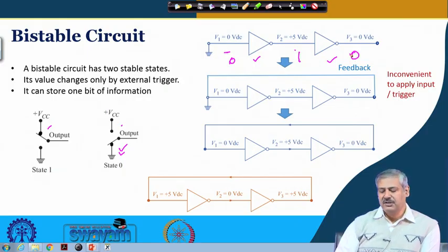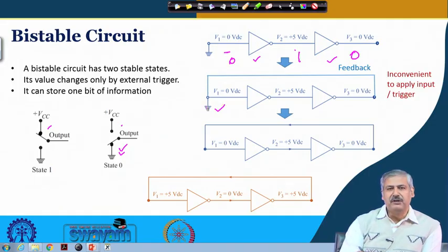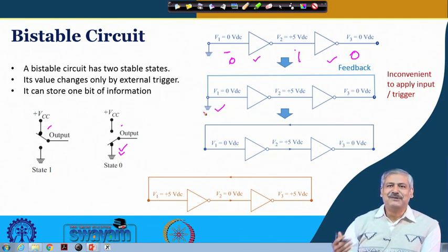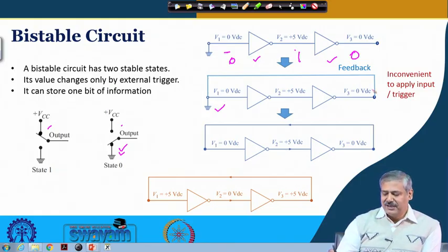Okay, this is understood. Now, while this ground is there, you connect a feedback. So, this feedback is key. This feedback is very important in developing the basic cell and the sequential logic circuit, right. In the combinatorial circuit, we didn't include feedback. So, the feedback comes in the sequential logic circuit discussion. So, you connect a feedback the way you have seen from output to the input, right.